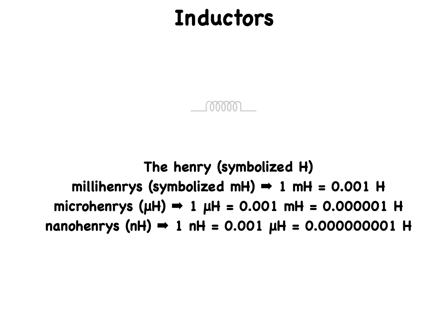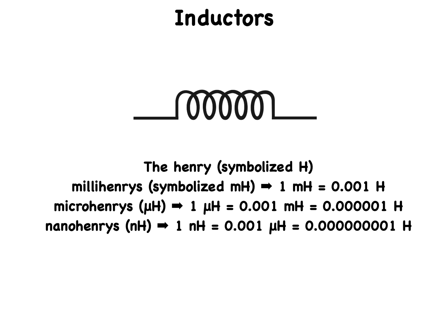The basic schematic symbol for an air core inductor has two leads which are designated by straight lines that merge into the coiled part. An air core coil has nothing inside the windings that can affect the inductance. Some air core coils are wound from stiff wire and support themselves mechanically, and their cores do, in fact, comprise nothing but air. In most cases, however, a non-conductive and non-inductive form made out of plastic, mica, or ceramic material serves as a support for the coil turns, keeping them in place and enhancing the physical ruggedness of the component.